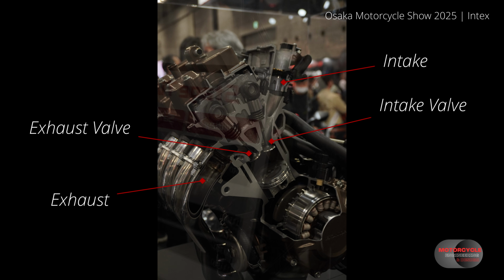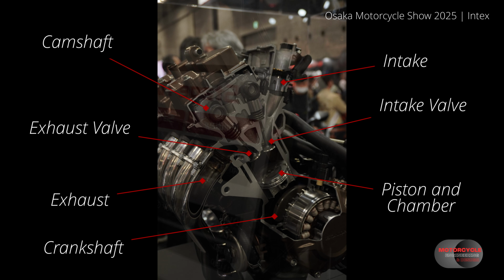The valve opening timing is controlled by the camshafts and the camshaft's relationship to the crankshaft. The camshaft rotates at half the speed of the crankshaft and is assembled in a way to ensure that the valve opening is in the perfect timing relative to the pistons, which are mounted to and governed by the crankshaft. So the crankshaft, camshaft and cam chain ensure the relationship between the piston movement and the valve opening, hence why timing and chain tension is important. And lastly, for gasoline engines, spark plugs.